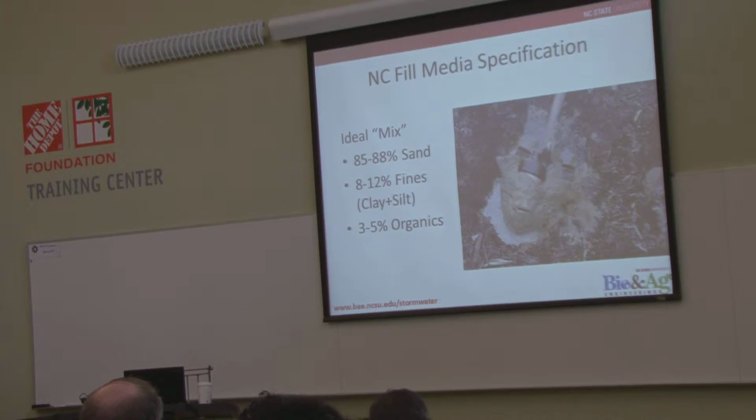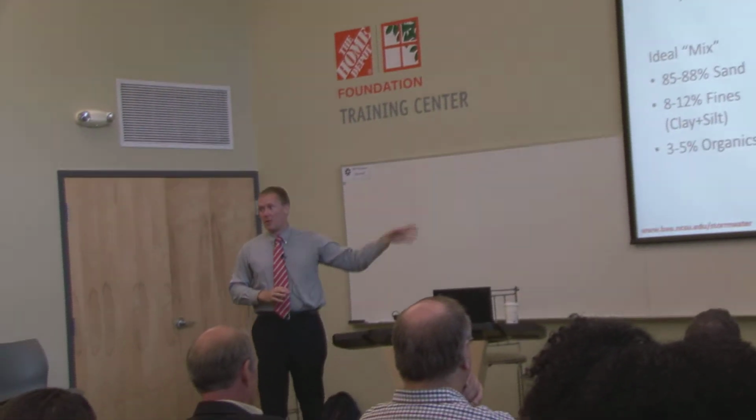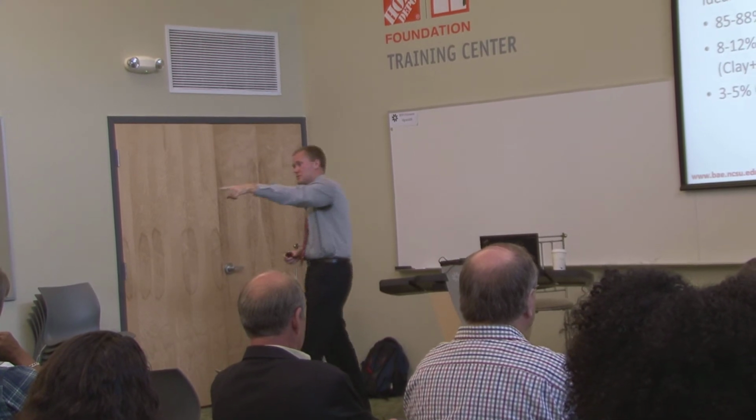If you gave that to a soil specialist, they would tell you this needs to be fertilized. But we have a lot of water coming to this bioretention cell. It has a lot of nitrogen and phosphorus in it. And so the water is what's going to take care of your plants. Plant growth is not a problem at all in this. We've had years and years of experience with it and no issues with plant growth.